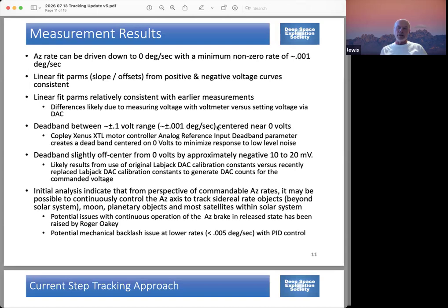And our encoder resolution is around just about half of that. So at some point, when you get below 0.01, probably somewhere around 0.005, we're not getting real timely updates from the encoder because it's waiting for the resolution to exceed the bit flips.